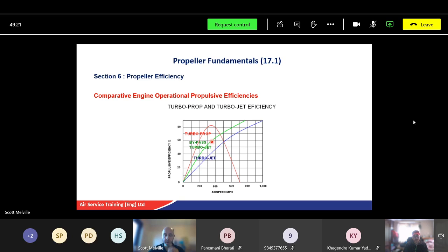What I mean by a bypass engine is we have air... A bypass engine, especially in a commercial aircraft, which are high bypass engines, is what it sounds like. It bypasses the core air. You basically have a propeller on the front, but it's not a propeller, it's a fan encased in a casing, and we call that bypass. And it is the cold air from a bypass engine that actually provides about 80% of the thrust. But again, don't worry about it for the moment, we will learn more of that in module 15. Certainly for low speeds and more efficiency, we tend to use a propeller engine.